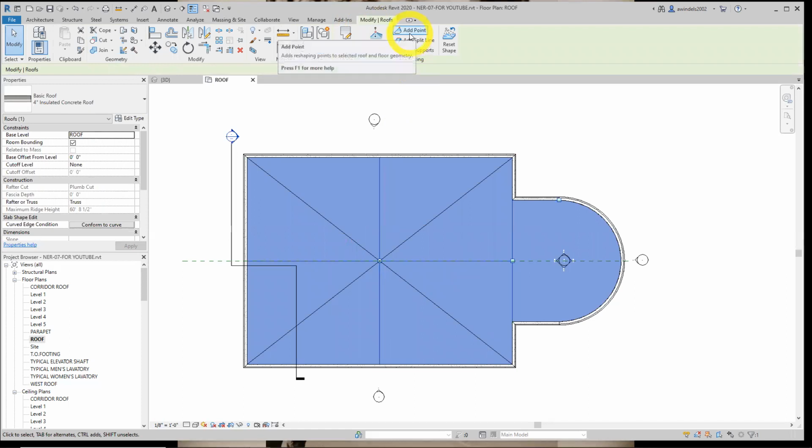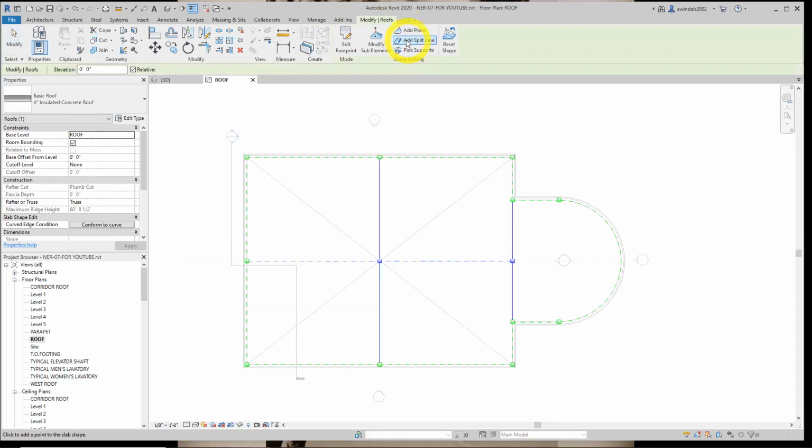And I selected my roof. I hit add point. Now I'm using these midpoints, those temporary lines I just made when I was outside of modify roofs. Now I'm back in it. Place one there. I'm gonna use the midpoint snap. That's the whole reason I drafted these temporary lines, to do just this quickly in a diagonal fashion. Okay, we got those picked.